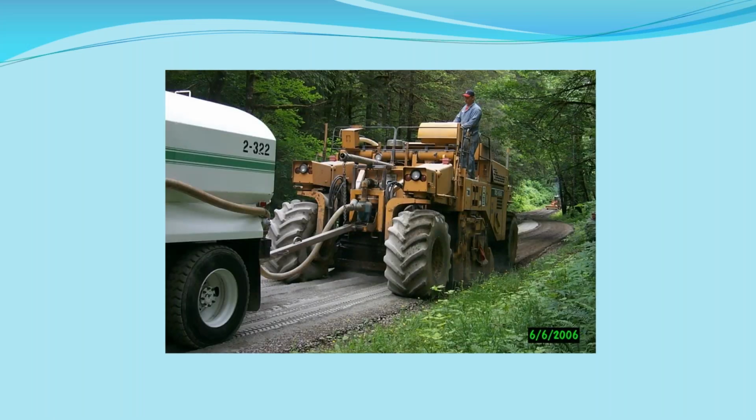Now, a lot of agencies that I've worked with over the last couple of years, a number of different agencies have actually come in and bought this grinder. This is a cat grinder. There's a couple of different brands of them. You can hook a truck up with your mag chloride or your lignin sulfate or your other type of chemical, and they'll actually grind it and mix it down into your roadway.